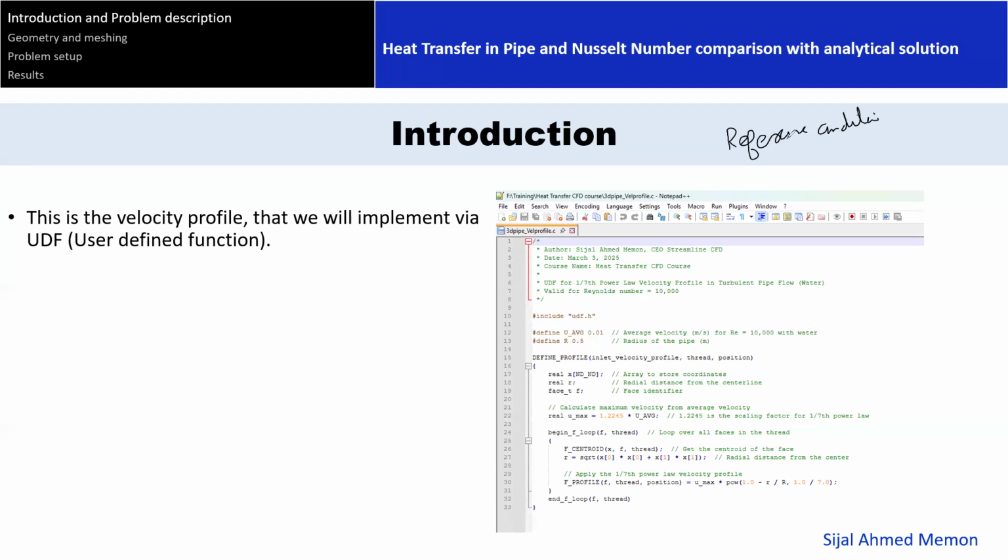So it depends. Similarly for velocity, those conditions are not going to be changed. Number two, they define the flow character. Number three, they will be there always. For example, in any simulation, the inlet velocity is the velocity that will not change, for example 40 meters per second for a vehicle body, or 1 meter per second for pipe flow. I'm just saying the numbers, whatever they can be, but those numbers never change, whatever happens inside.